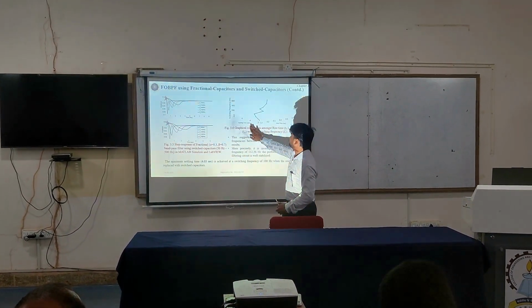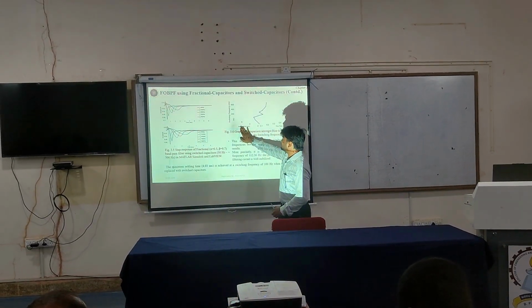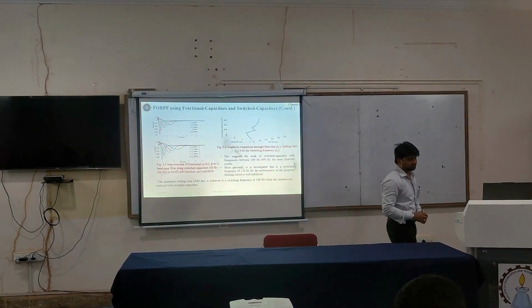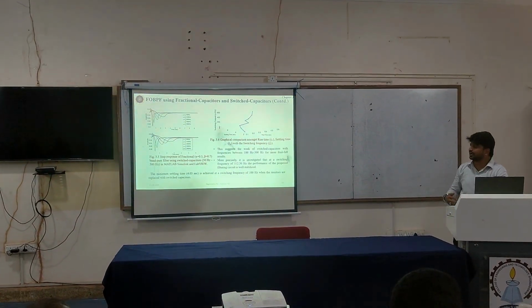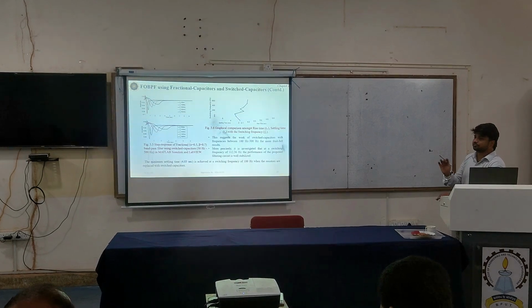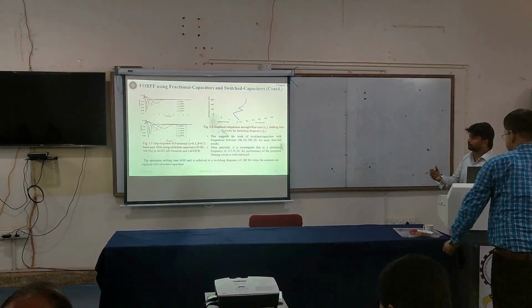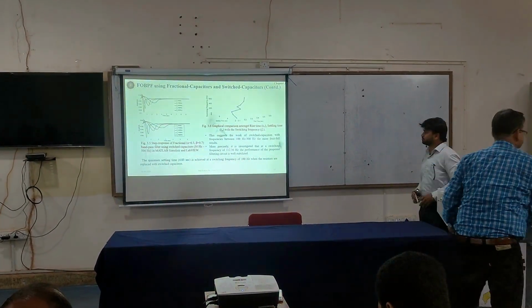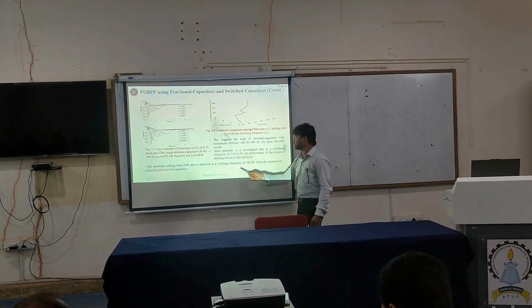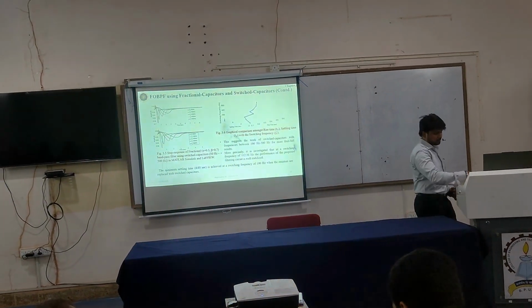This plot shows how the switching frequency depends upon the settling time and the rise time of the fractional order bandpass filter. It has been seen that if the switching frequency is between 100 to 300 Hz, it gives more favorable results of low settling time, and the minimum settling time, that is 4.03 seconds, is achieved at a switching frequency of 100 Hz.